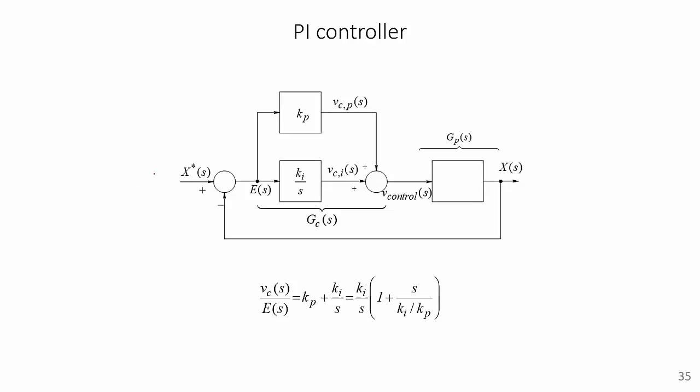So what does a PI controller do? You have a reference signal and you have a feedback of that signal that's measured. For this case, we are measuring the speed of the motor. This is the reference speed that we want. Let's say we want the speed to be 100 radians per second, and the measured speed is at 90 radians per second. So we find the error signal, the difference between the two, which ends up being 10 radians per second. And we apply a proportional gain, let's say a gain factor of 1. So we end up applying 10 times 1, a voltage of 10 volts,